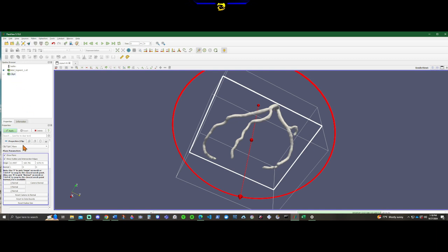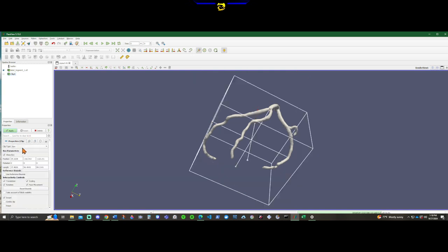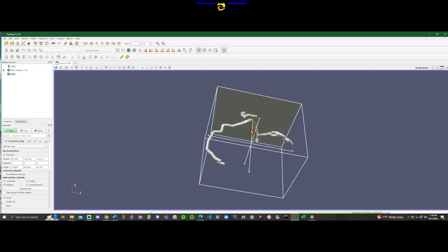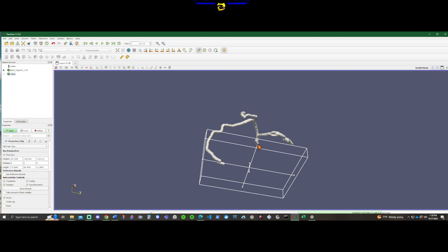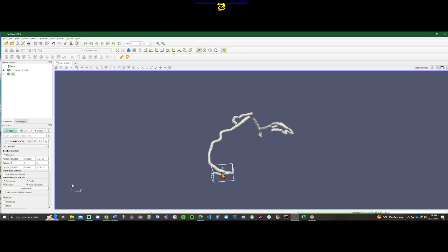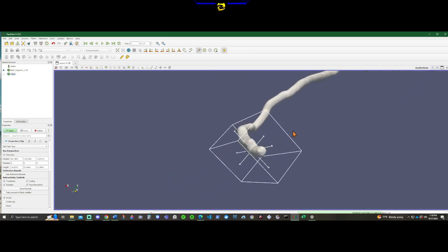But let's focus on the clip. So the biggest thing is for the clip type, you want to choose box, because every other clip type is for very symmetrical models, and what we're working with is nowhere near symmetrical. Drag this box to fit the sort of shape that you need, and then similar to 3D Slicer, use the middle click button, the middle scroller button to drag.